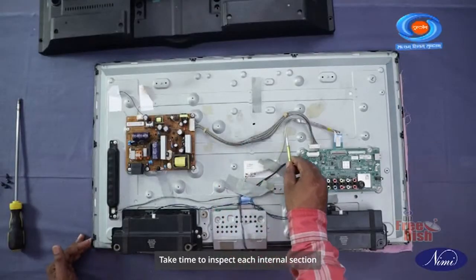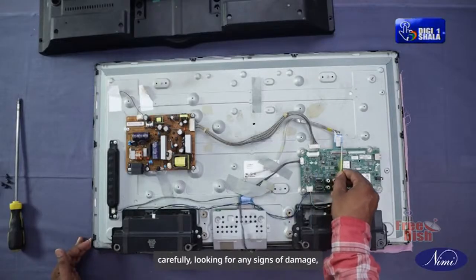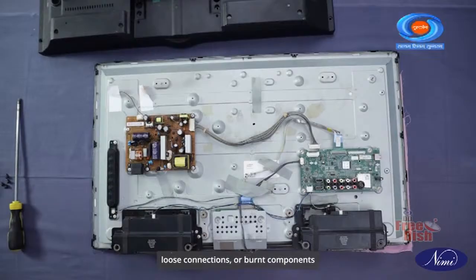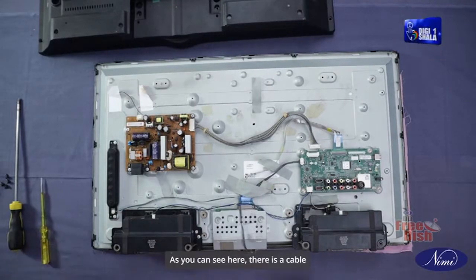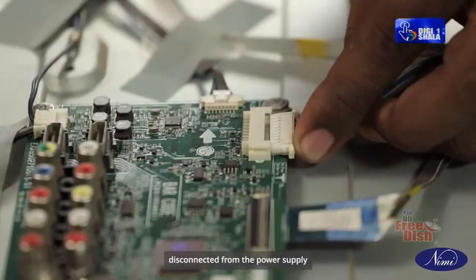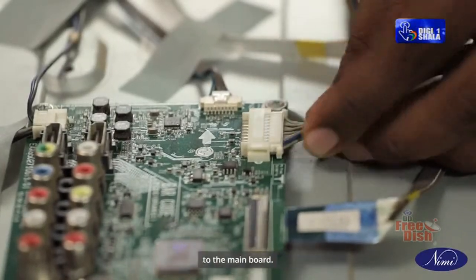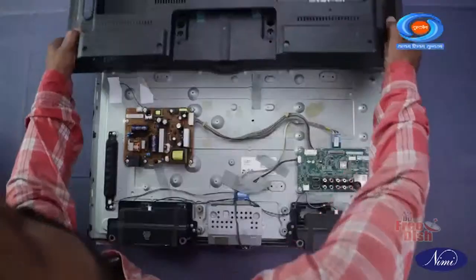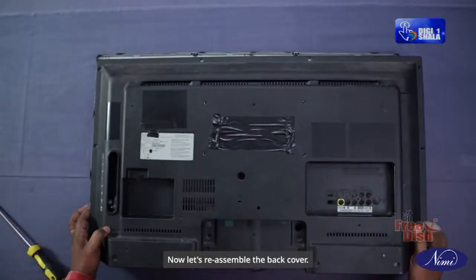Take time to inspect each internal section carefully, looking for any signs of damage, loose connections, or burnt components that may indicate a fault. As you can see here, there is a cable disconnected from the power supply to the main board. We need to connect it and test the TV. Now let's reassemble the back cover.